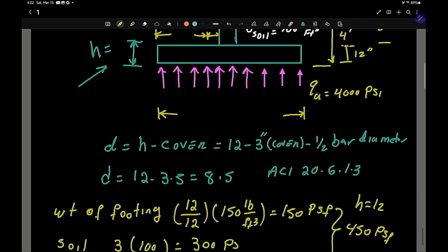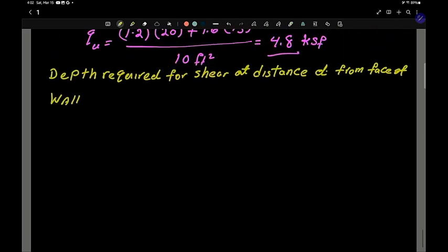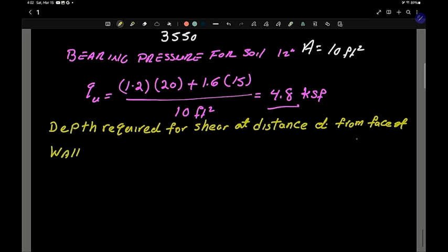So if I come back down here, it's basically like a cantilever. And the load is going to be, shear is going to be basically the load itself, and moment is going to be WL squared divided by 2. You remember that from kindergarten, right?